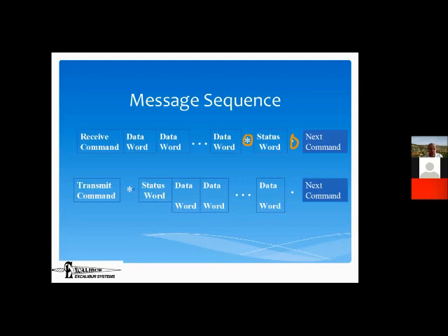And there are a number of options. One option is split it into 2 buses, right? This is not simple to do, both in terms of the wiring and in terms of the logic, because the 2 buses can't easily talk to each other. In fact, they can't do it at all over the 1553 bus. The same bus controller or the same mission computer might act as a bus controller to both of them, and then it can play games. So obviously that's complicated, and you want to avoid splitting things into multiple buses if you can. But that's one of your options. There are a few others.